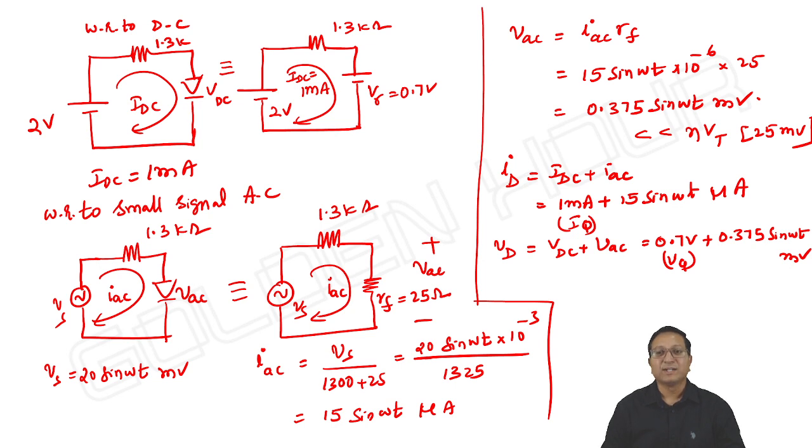This is known as small signal analysis. It is not superposition. The effect of AC can be studied from the values of current and voltage, especially the current you are getting from the DC analysis. The DC is responsible for the conduction of the device. After the conduction, the diode is able to respond to the millivolts of AC signal we are applying. Then the small AC variations of current and voltage can be obtained using this small signal model. A linear relation you are able to bring.